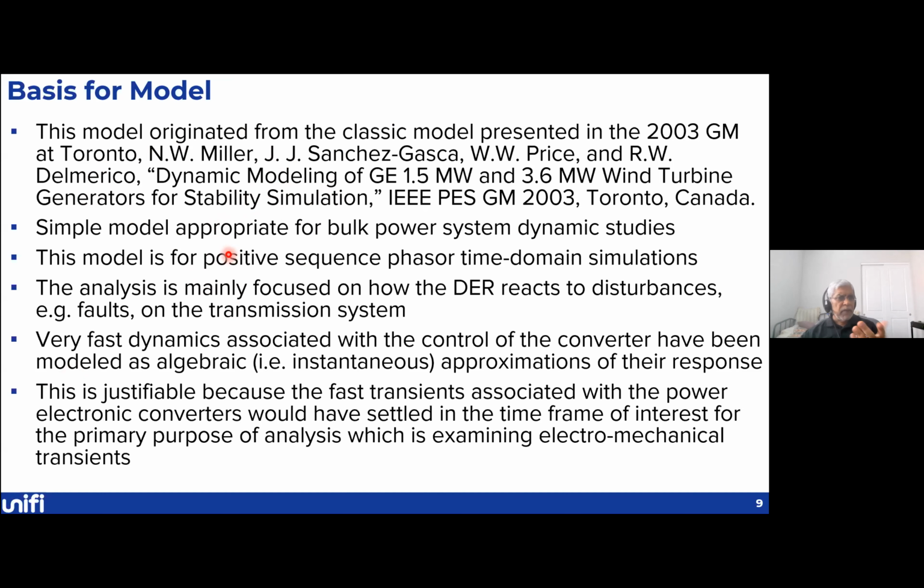It was a very simple model appropriate for bulk power system dynamic studies, and very clearly stated that this was purely for positive sequence phasor domain, time domain simulations. And the analysis primarily focused on how this distributed energy resource reacts to disturbances, for example, faults on the transmission system, and how it impacts the transmission systems.